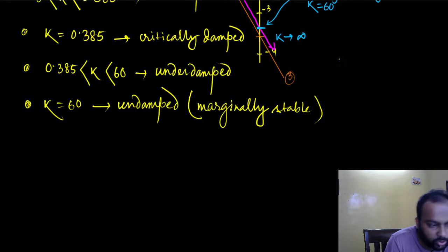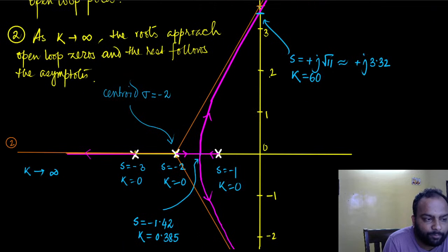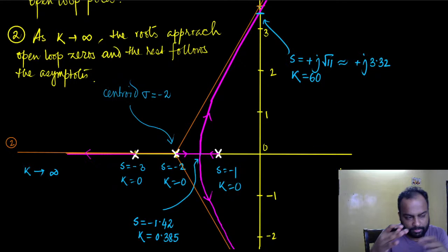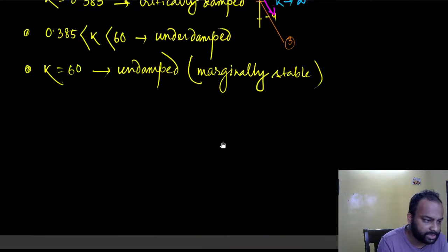Just one more thing, also keep in mind that if I have 2 poles on the j omega axis but I have a pole here maybe, then there is no point of saying undamped or anything, it's unstable, right? So the rightmost poles take precedence when talking about how the damping is. Okay, so the rightmost poles would take precedence here.